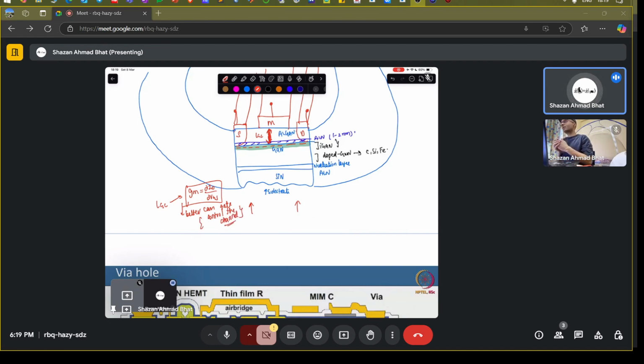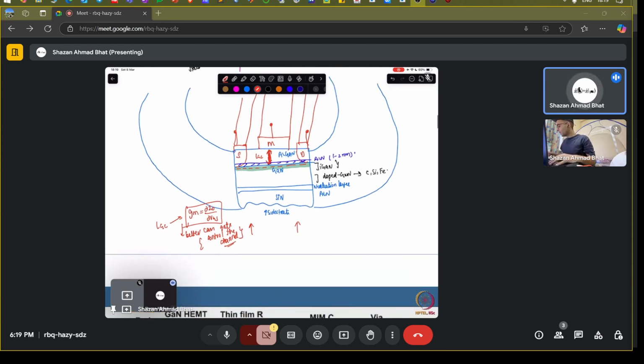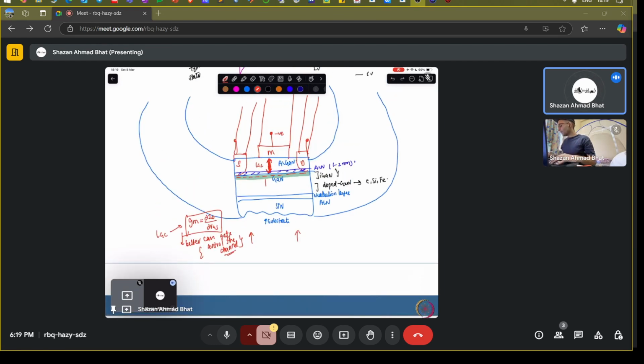That's why it's a field effect transistor, because it's capacitively coupled. You are applying some voltage here, let's say a negative voltage, that is coupling capacitively. That field being created is repelling or depleting this channel, so the channel is getting depleted. That is the coupling we want, and you want this capacitive coupling to be large so that you can control the transconductance parameter.